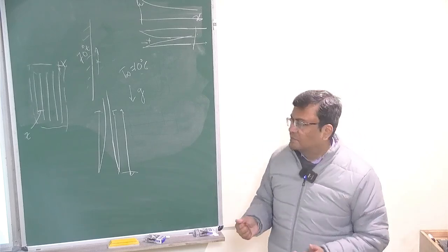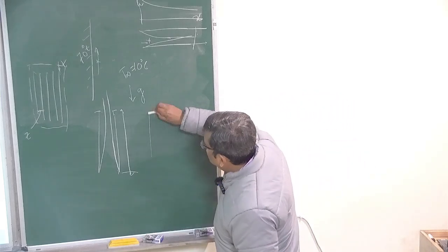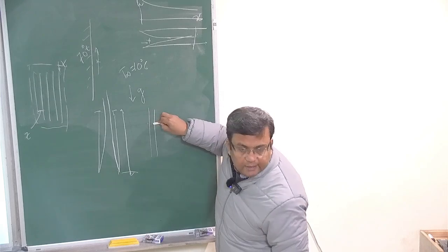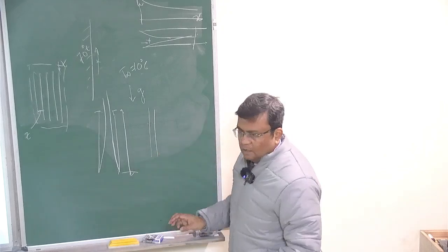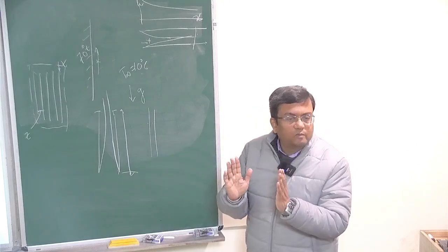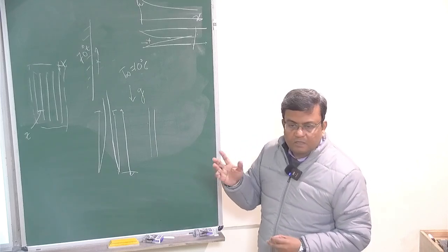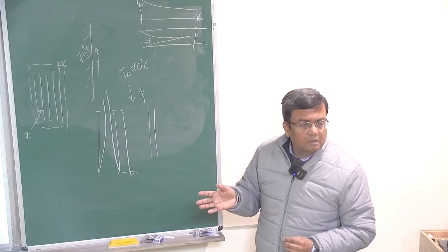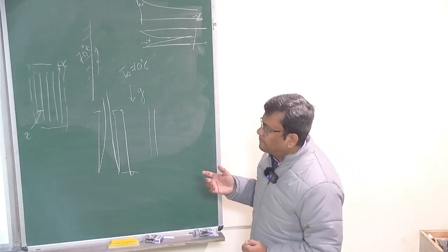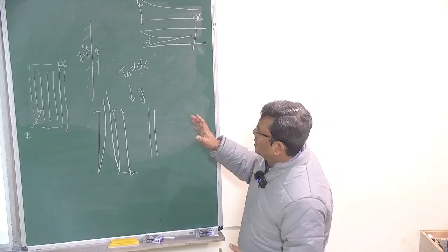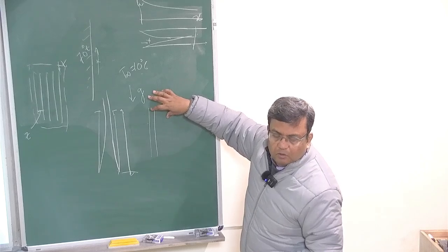So how do you get an optimum? The way you get an optimum is like, okay, you have two fins which are very close to each other. You don't like that, and you try to increase the distance. At one stage, the boundary layers will start to separate out from each other, and you will get more isolated boundary layer. But you don't want to go to that level, because then the number of fins also you are losing. Okay, the number of channels is also coming down. So you stop where it just becomes large enough. Okay, right? Not too small, not too large.